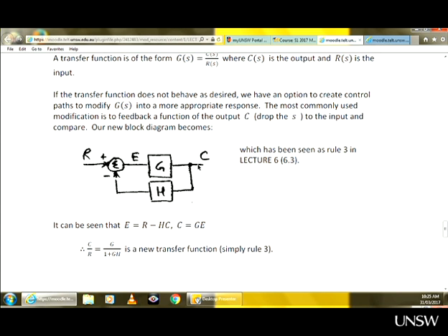If anything changes, for example, you come across a hill, then obviously the car will slow down. Your sensor will notice that now you're doing 55, and this is where the difference is generated. This error signal will tell you it's 5 kilometers per hour less than what is required. That will increase the fuel intake, increase the RPM of the engine until you reach 60 again.